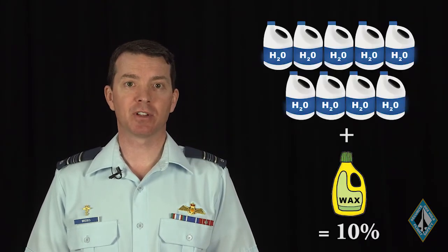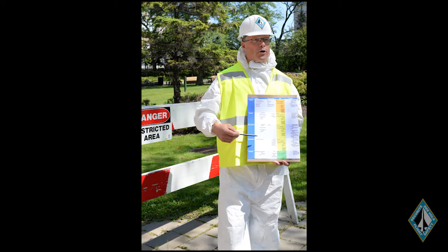For example, a variety of chemical and biological hazards may be eliminated by decontaminating the site with a water or 10% bleach solution. Explosive hazards may be eliminated by explosive ordnance disposal teams. Burned carbon fibers may be stabilized by applying a fixant or soil tackifier, such as water, ice, firefighting foam, or a 10% acrylic floor wax solution. In addition, exposure to all categories of hazards may be reduced by strictly limiting and controlling access to the site. In short, multiple control measures should always be considered on a crash scene in addition to the use of PPE.